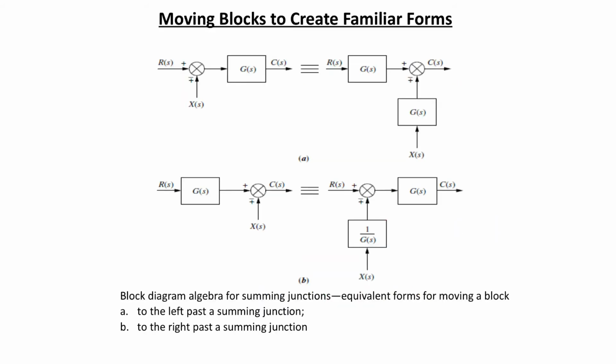Before we discuss the reduction of the block diagram, we will discuss moving blocks to create the familiar forms. It is not always the case that the familiar forms are apparent in the block diagram. For example, suppose we have a system in which we have a summing point, and after that summing point we have a pick-off point.